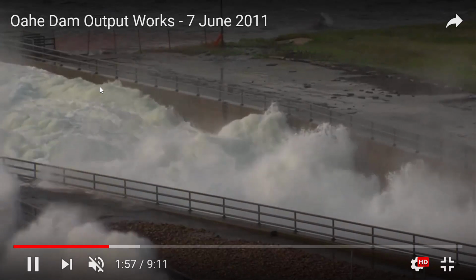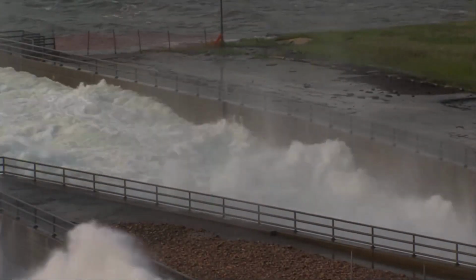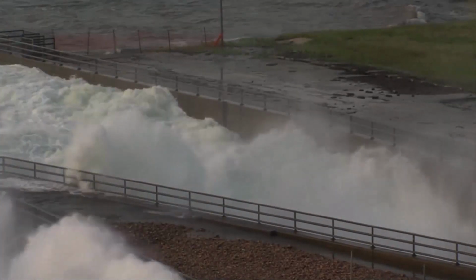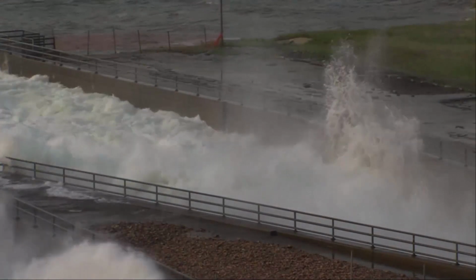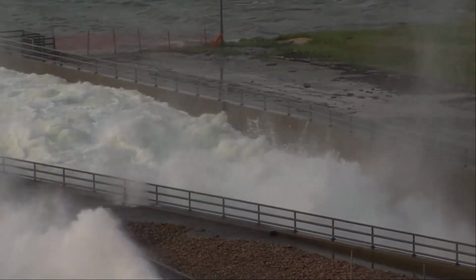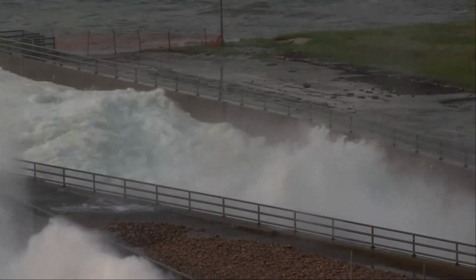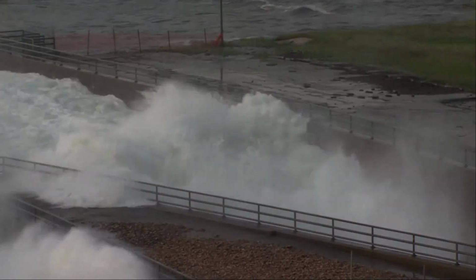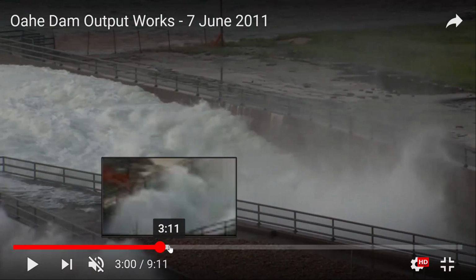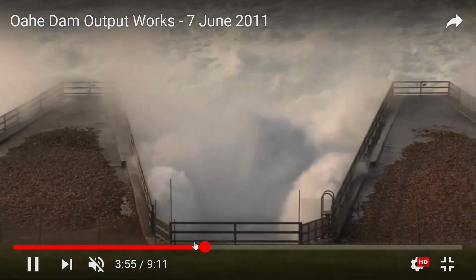But if they allowed the velocities to stay high as the water moved downstream of this overflow spillway, then it could cause a lot of scour in the river, and that leads to deposition downstream, where it could clog some of the locks and dams like we have here in the Huntington area. They have locks and dams and hydraulic structures downstream that they don't necessarily want a bunch of sediment clogging up. So they try and have as much energy loss as possible in a certain location.